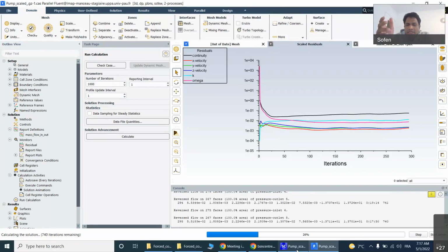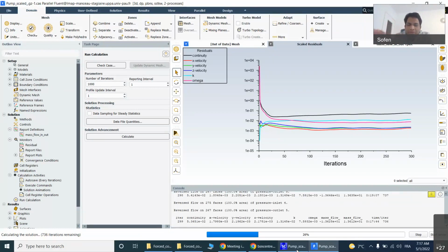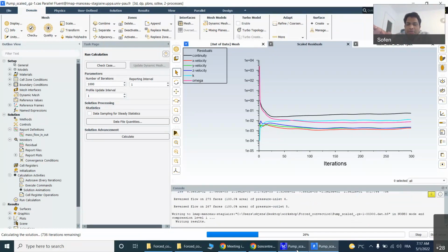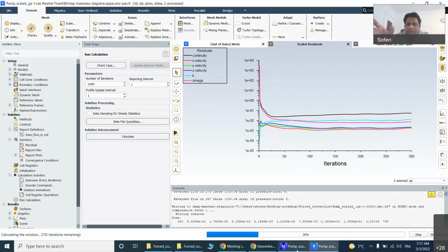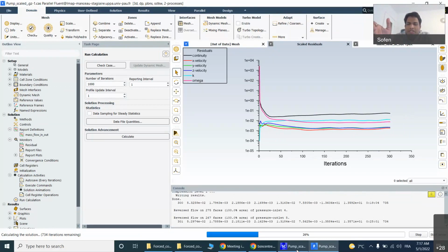So these are the requirements: we take inlet pressure and outlet pressure as input, just like our boundary conditions. The turbulence model is the mathematical part. Based upon the available literature, the available turbulence models, and computational resources, we have to choose.